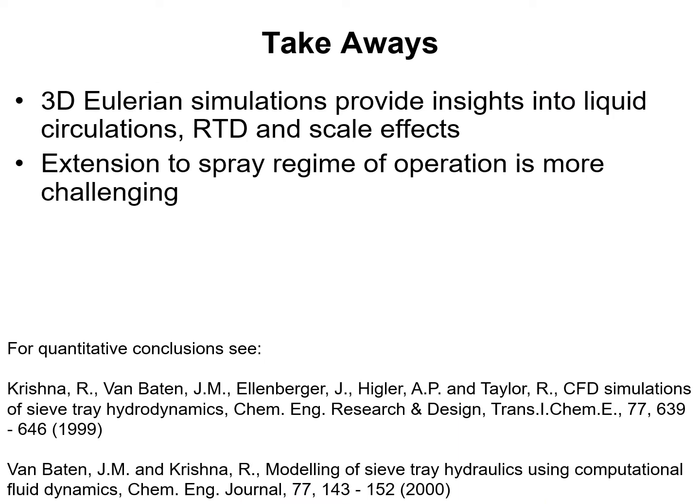We have presented results of 3D Eulerian simulations that provide some insights into liquid circulations, residence time distributions, and scale effects on sieve trays. These simulations were performed for the bubbly flow regime of tray hydrodynamics. The extension to the spray regime is more challenging.